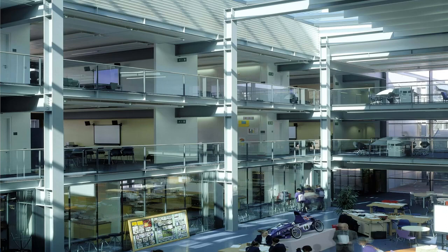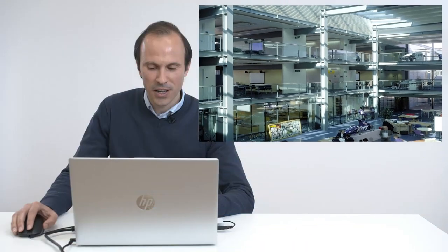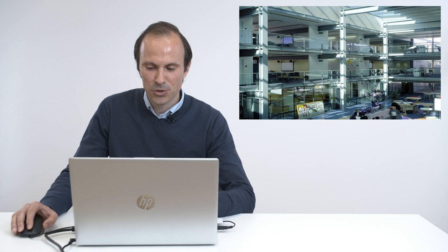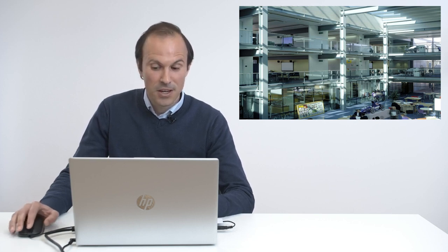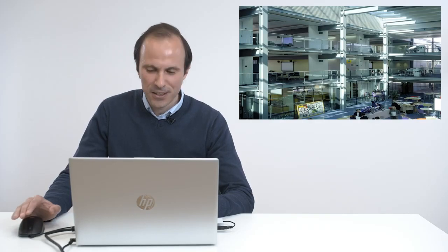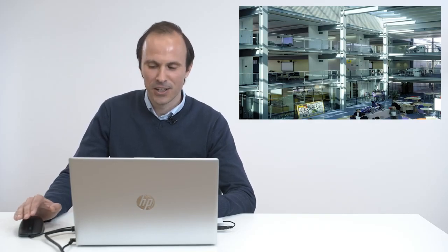This is the inside of the building, and this is where interesting things for us acoustically start to happen. So in order to foster the open space approach and collaboration, communication between the spaces, classrooms were designed without the back walls. You can notice that on the image. And by doing so, by removing the back walls, the classrooms were connected to this large interior atrium. So what actually happened on the very first day of the school? The noise between the classrooms resonated so much through the atrium that students were not able to hear the lecture.